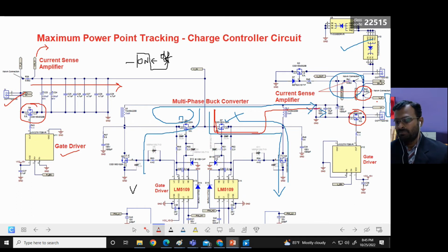or the battery. In case the battery is drained, say for example, there is a lower cutoff value for the battery, in case the battery is drained, at that time also it will disconnect. Or if the battery is over discharging, like the load is taking too much current, at that time also it will open the switch so that the load will be isolated, or disconnected from the battery. So this is the important function of the circuit diagram.